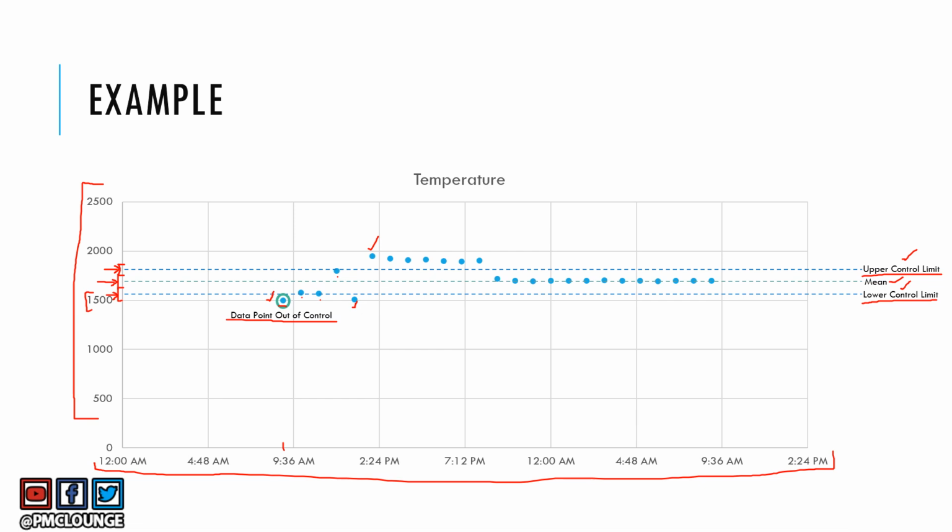So when you have 7 points, that is when you should know that your process is out of control. You have a problem. So when you see this, you need to look into it and try to figure out what's going on, what's wrong. And this is known as rule of seven, as you can see here, rule of seven.